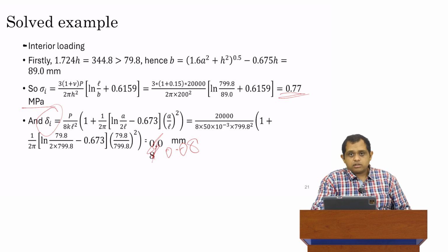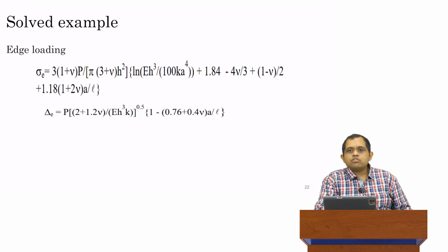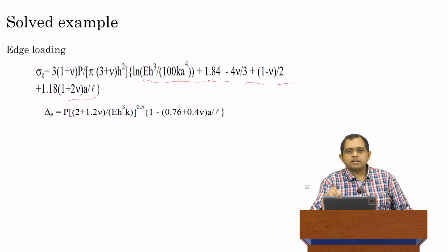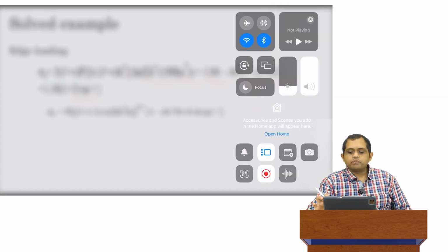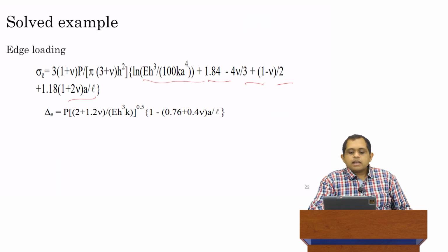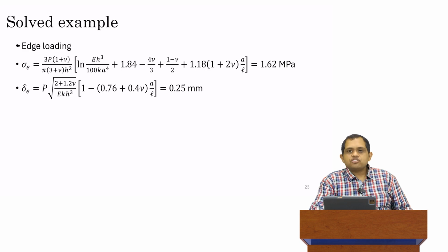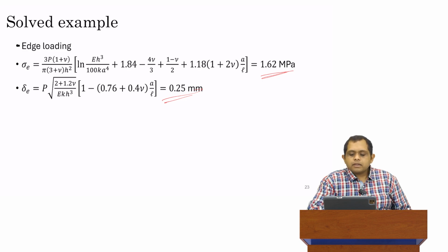So pretty small, if you recall. We'll compare the values in a second. But now coming to edge loading, basically the same formula. I'm not going to repeat this, but again, there are many terms over here. Please evaluate the terms one by one and then perform the necessary operations. Don't try to evaluate the entire expression in one go. Okay, I did the substitution, so you can just check if the values are fine. The stress comes out to 1.62 and the displacement comes out to 0.25.